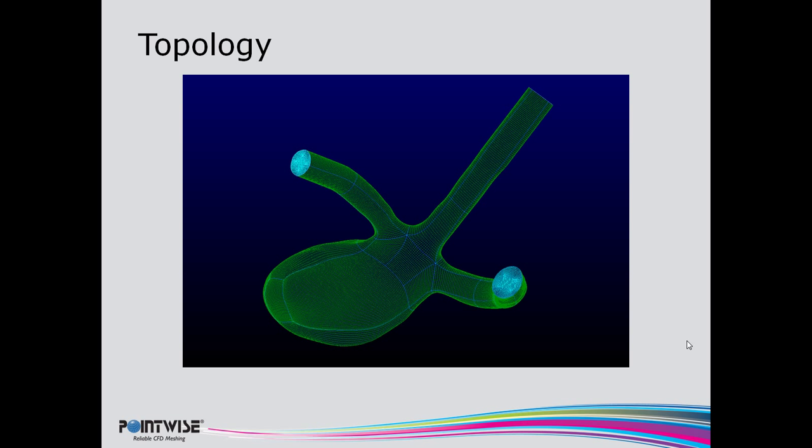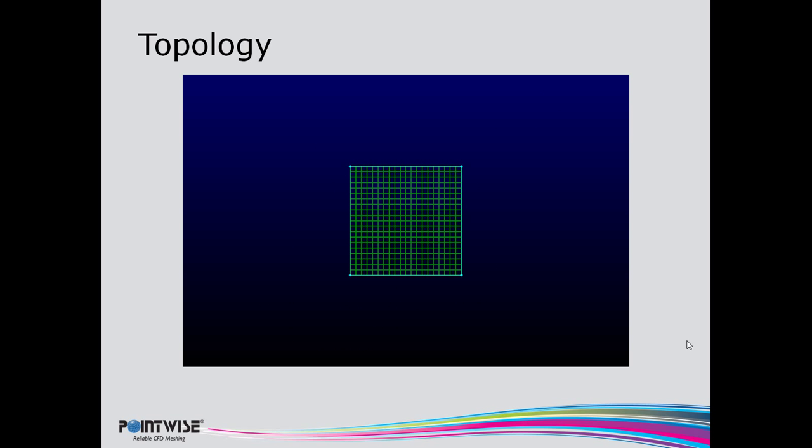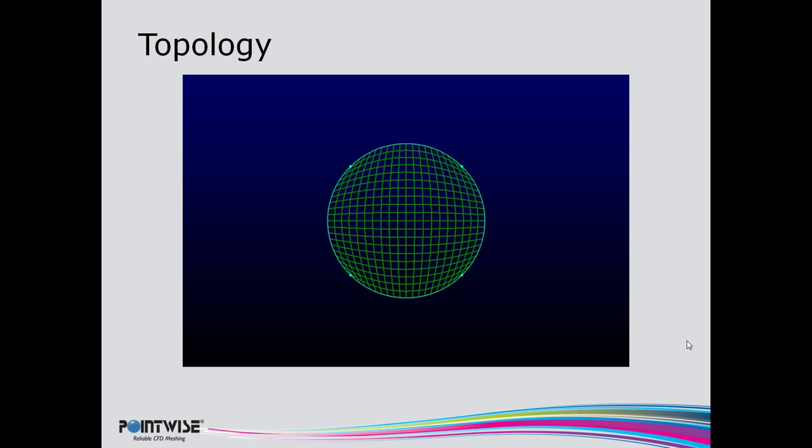So speaking of this circular geometry, since we're dealing with structured meshes, it requires a little bit of extra topology that I'm going to try to introduce you to. If you have a perfectly rectilinear system, a structured mesh is very easy to apply. You can see for a square like this, opposing grid lines are simply connected and you have a perfectly decent mesh. However, whenever you go to a circular domain, all of a sudden you have very skewed cells near the junctions of these adjacent corners due to the curvature of the connectors at the edge of the domain.